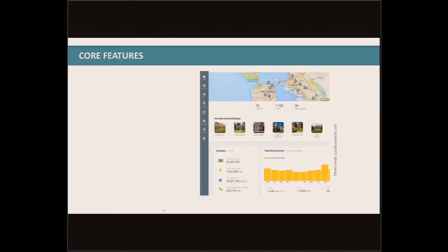The core features of an energy management system is, number one, data visualization. We want to take interval data from the different meters, so from our electrical meter, gas meter, water meter, and also want to take a look to see if sub-metering certain pieces of equipment would be of value. If we've got very high energy intensive pieces of equipment, say compressed air, refrigeration compressors, whatever the case may be, some of those would lend value to be able to sub-meter those and see how they operate in conjunction with the overall energy picture of the facility.